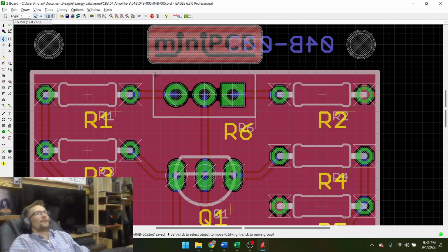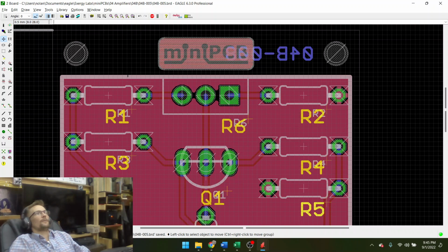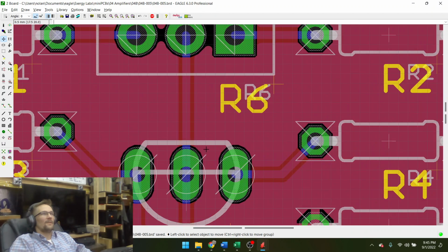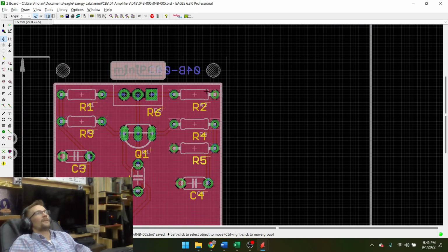Now my pot is sitting on that outline. I'm going to leave it for right now. It's not extending beyond, so you don't really notice. My silk screen outlines are okay. They could be thicker, but like this guy is just slightly thicker. That's thicker than those, and it shows up a little nicer. But the thinner ones are okay, so I think I could leave that.